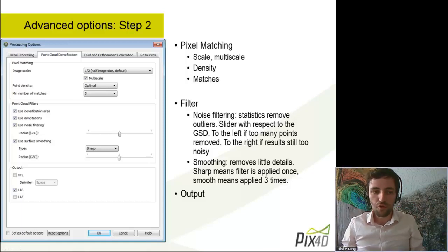We would recommend to go to full process image scale only when you have a camera which is extremely sharp, maybe like a Hasselblad type of camera, but usually you don't have any benefits with most point and shoots and DSLR cameras. However, this scale has a huge effect on the number of points which will be generated, and in a certain respect also the accuracy at which these points are generated and the speed at which these points are generated.